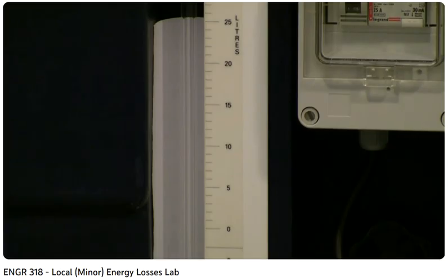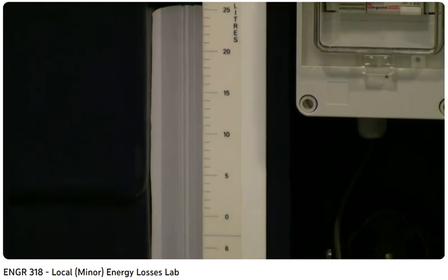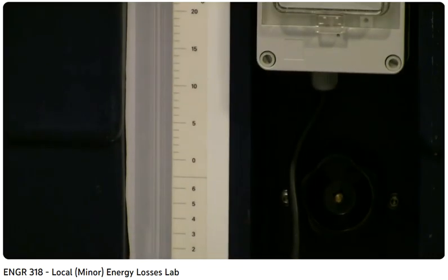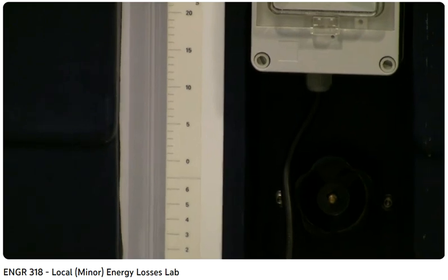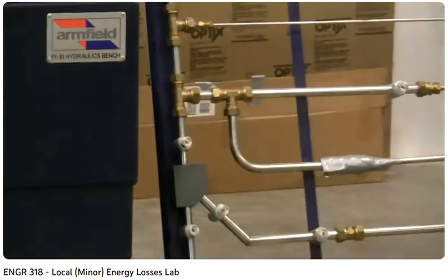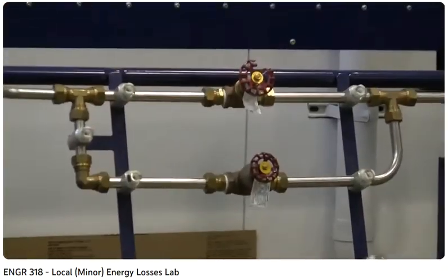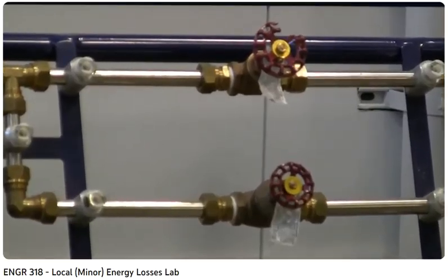Contrary to my previous suggestion that we wouldn't be adjusting the flow rate with this valve, looking at the data sheet again, I realized that we're supposed to quantify the gate valve with it fully open. The K values that I have provided for gate valves are for a gate valve when it's fully open. And so what I've done is I've opened up the gate valve here in setting 1, flow path A. The gate valve is the one on top there.